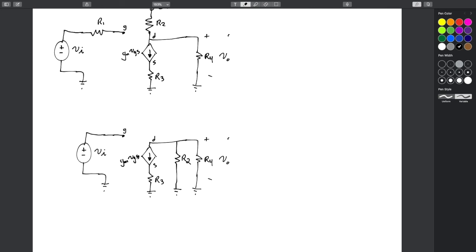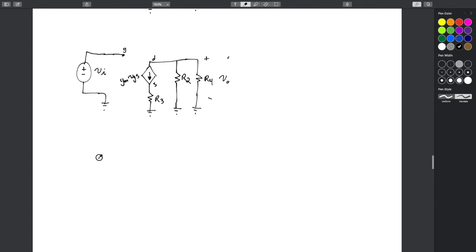This is basically the small signal model, or equivalent, of the circuit up above. We've substituted in the MOSFET equivalent, this little current source. There's an input voltage of some value, and then we can see the resistors right here collapse together, and they're in parallel. So this can even simplify further to just what? The input small signal voltage to ground, and then we could do nice and clean.